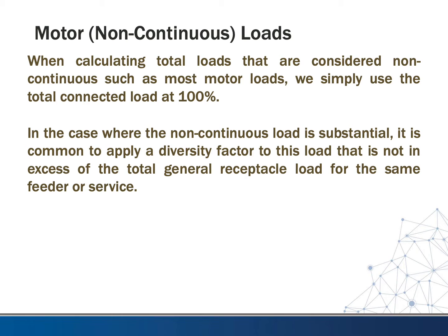In the case where the non-continuous load is substantial, it is common to apply a diversity factor to this load that is not in excess of the total general receptacle load for the same feeder or service. So, in other words, if we have a really large non-continuous load and we have a large general receptacle load and we see that our total receptacle load is reduced by some percentage, we usually can apply that same percentage